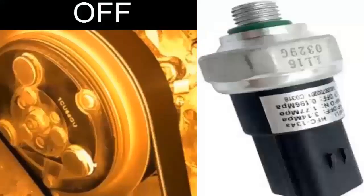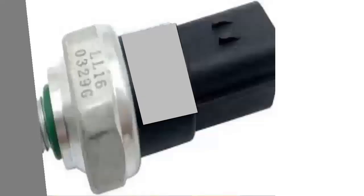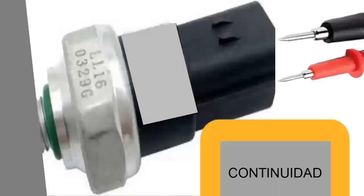How to test the low-pressure switch. A. Turn off the vehicle. B. Disconnect only the electrical connection of the low-pressure switch. Do not remove the switch itself. C. Use a multimeter to perform a continuity test on the switch's pins. This test should indicate continuity.